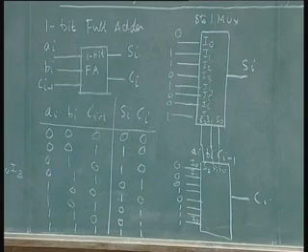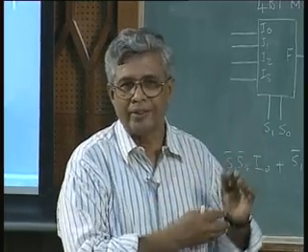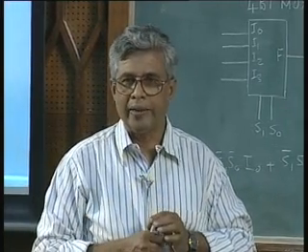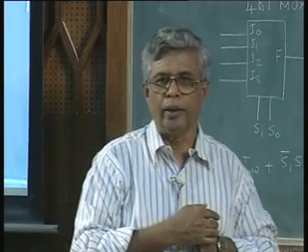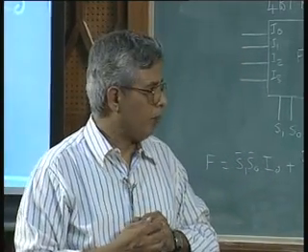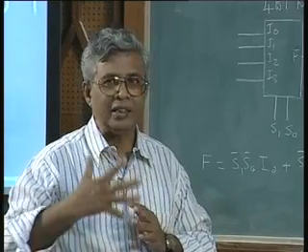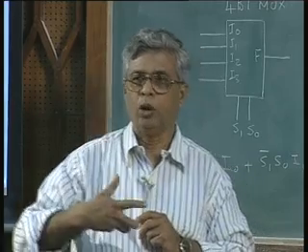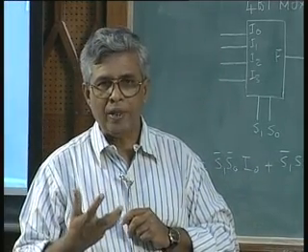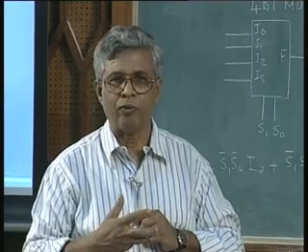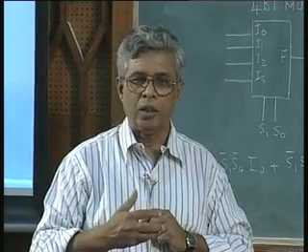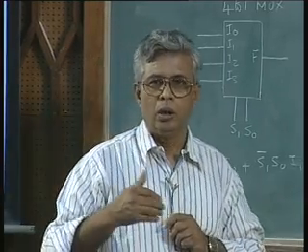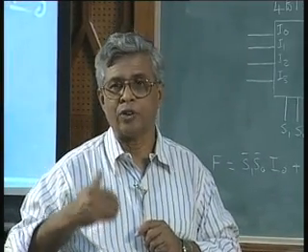Today that is gaining momentum, because this is only a simple example. Full adder, who would do this? Probably I would use exclusive OR gates and simple AND gates as you are used to doing in your previous course. You probably may think that is simpler than this, but think of this example growing to a larger number of inputs and more complex functions. So the mapping onto available components, especially the type of circuits we are talking about today, is important, because functionally they are equivalent to thousands of gates, tens of thousands of gates, hundreds of thousands of gates.